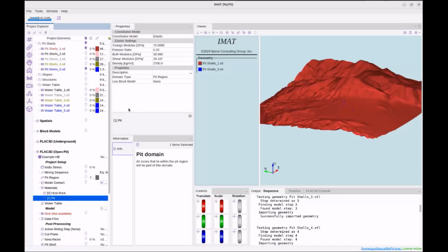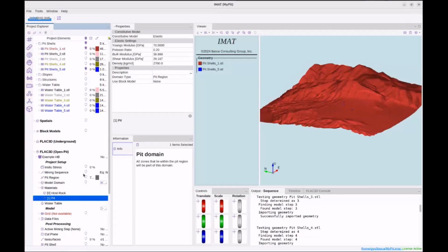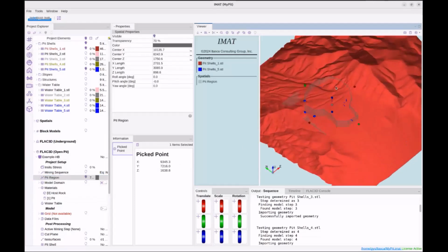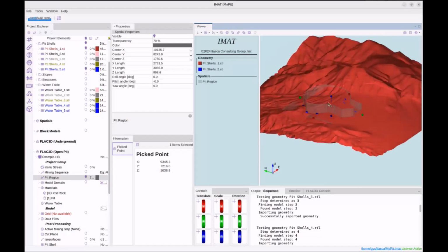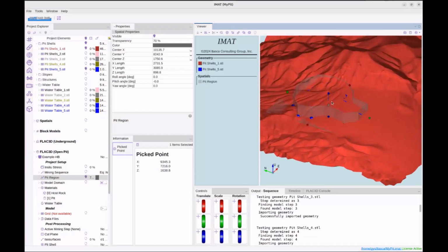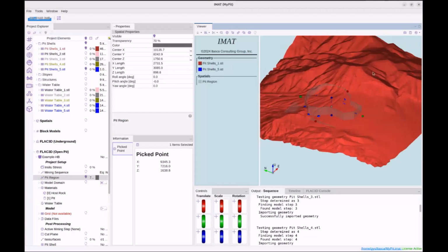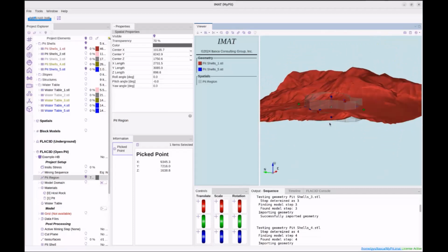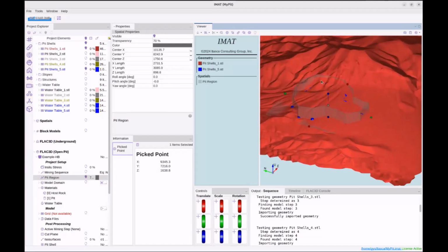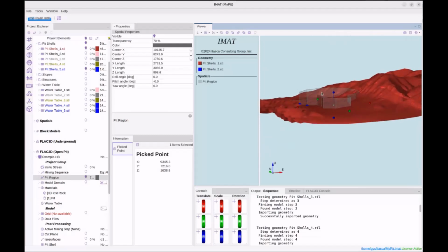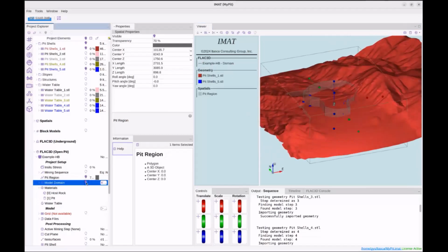Now, you may ask, why am I doing that? Well, one good reason is that if I only assume a plastic material inside this region here, the model will solve significantly faster. So having an elastic material outside the rest, and we're not really interested in the results outside. Only allowing for a plastic material inside the split region will speed up solving significantly, as typically what often happens